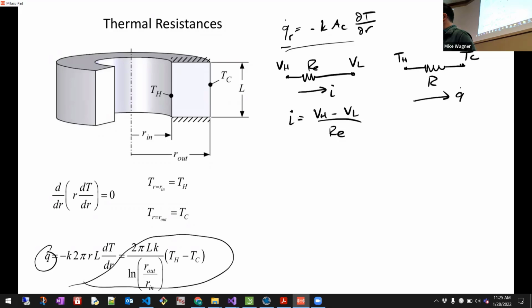You would have heat flow across that, right? So the relationship would be Q dot is equal to TH minus TC divided by R, right? So there's this kind of direct analog between these two things. I mean, this, again, is not that profound of an observation, except that if we start calling R, whatever it is that's multiplying our temperature difference, our potential, then we can compare R's, right?